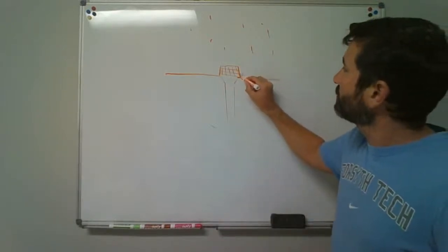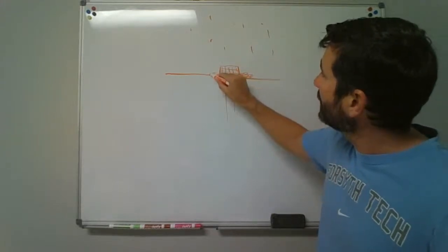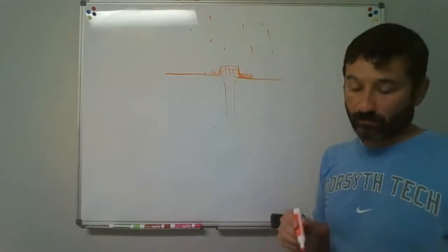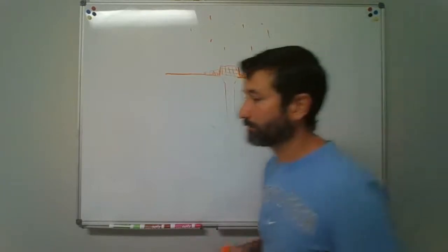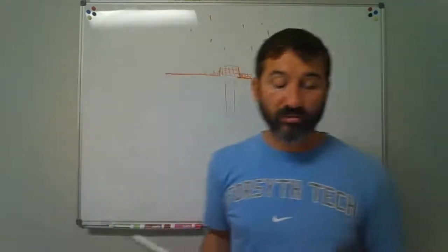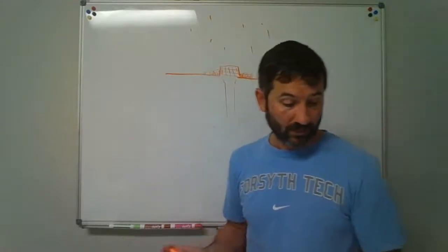Well, in case we get some debris that's built up, because as things wash towards this and build up around here, we want to still have area where water can go and go down this drain. Okay, and it says that it shall extend not less than 3 inches above for that strainer.